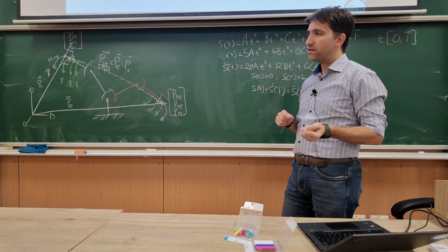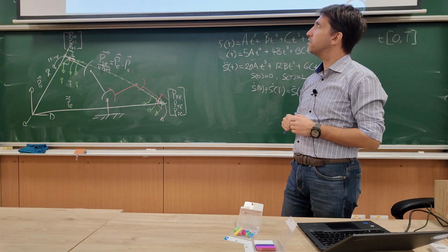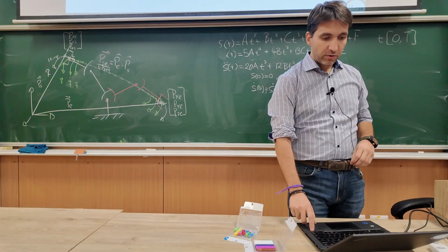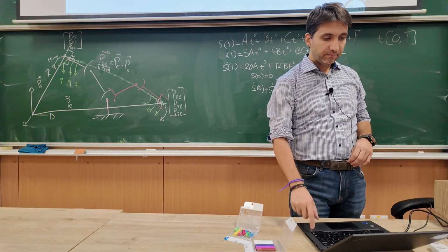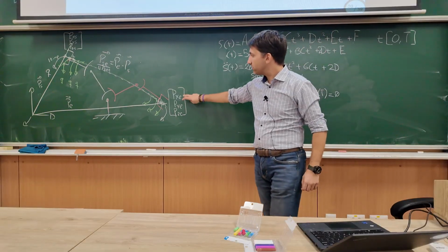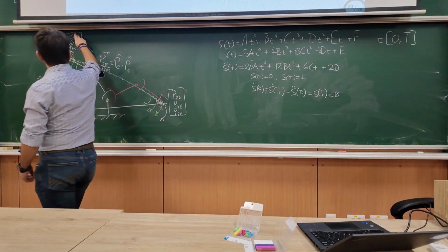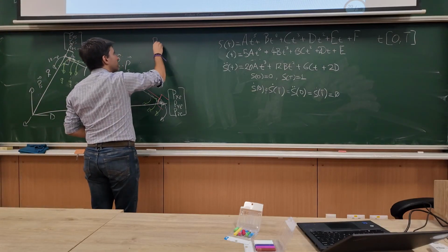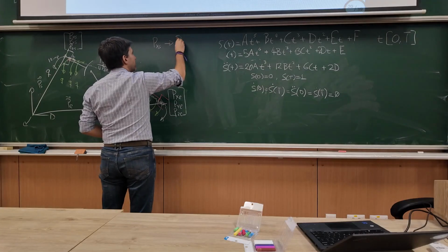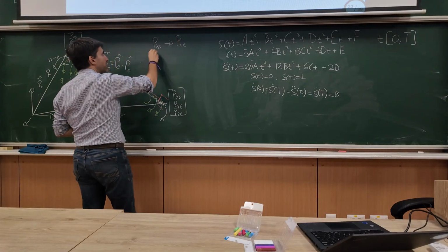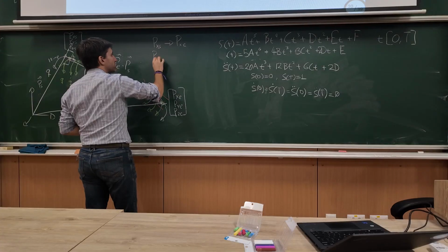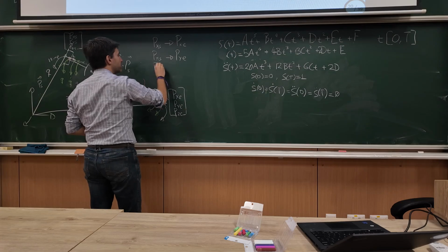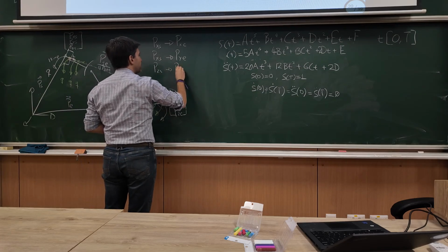But I have another idea, and I'll explain later why I think it's a little bit better. So let's move on because we don't have too much time. What we can do is interpolate each one of these three elements separately. Right? I can interpolate px starting to px ending independently, py starting and py ending, and pz starting, pz ending,